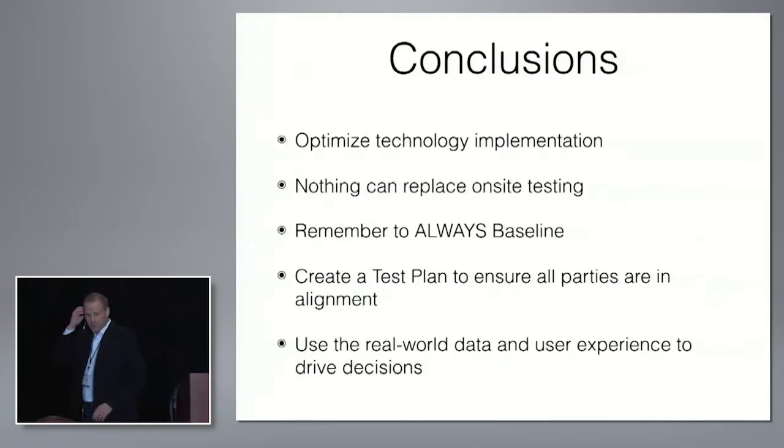So the conclusions: optimize the technology implementation. Think about the use case that you're using it in. You don't need to be blasting out 100 milliwatts if you only care about what's going on in a specific area. Set it to 1 milliwatt or 2.5, depending on what your use case is. Nothing can replace on-site testing. Nothing, because that's the real world. There's no theory anymore. It's what is actually going on.